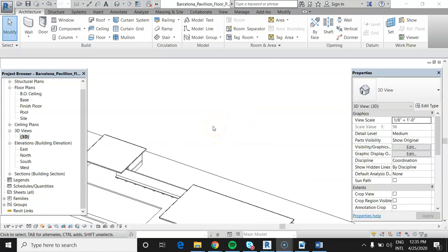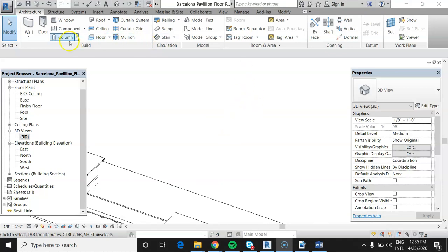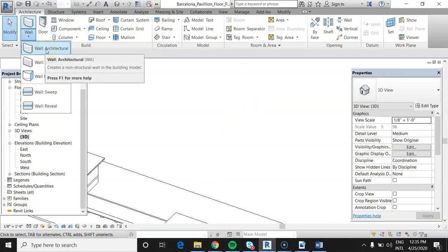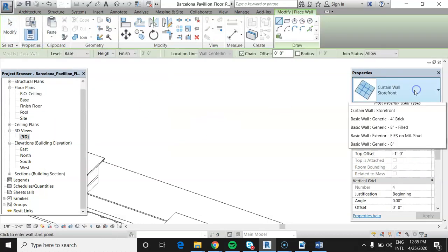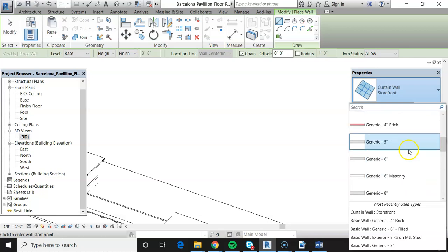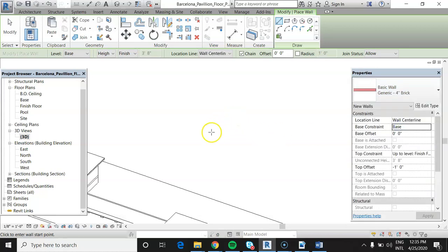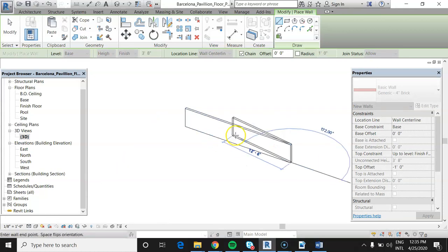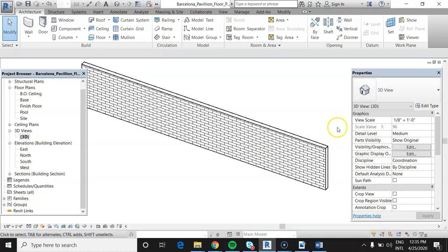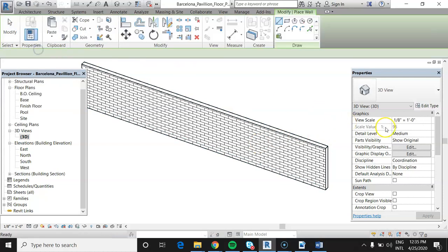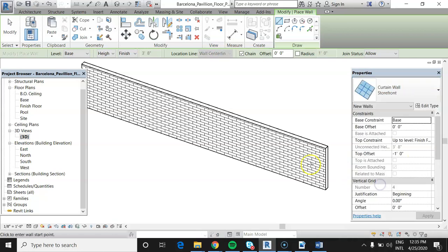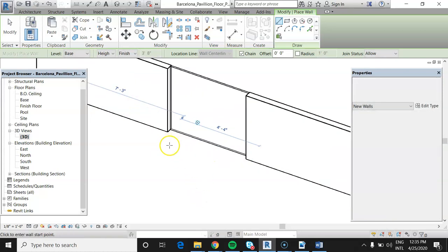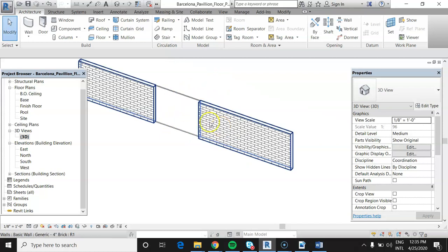I'm going to draw off to the side here for a moment. I want to show you what the embedded wall means exactly. So let's go to wall and pick a slender 4-inch wall. Draw that, zoom in a little bit. There's our 4-inch thick brick wall. Now let's embed a storefront in it. Scroll down, the storefronts live down here at the bottom, and we'll snap that right to its center line. And there it is.